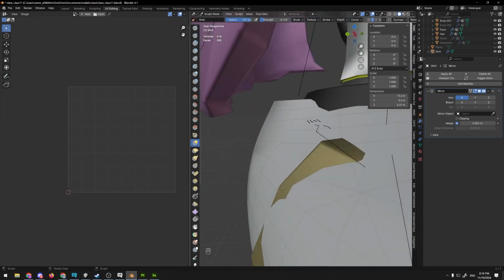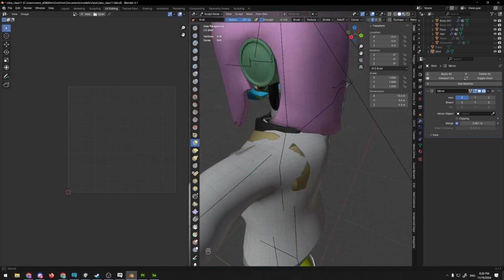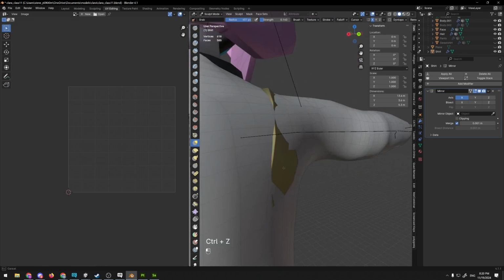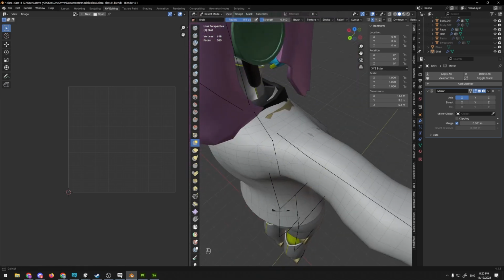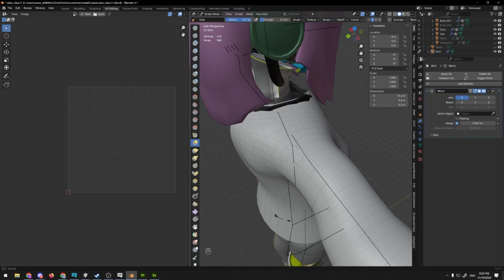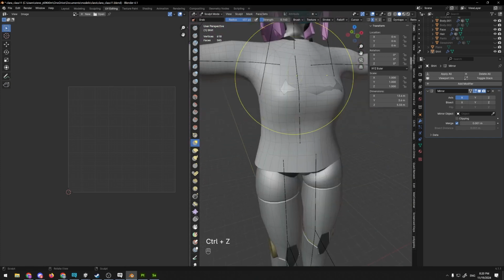This whole section up here, I'm just going to grab and move because, again, smoothing across symmetry lines doesn't work very well until you've applied the mirror modifier. And then, like I mentioned earlier, fixing these areas where we have clipping. Although we are also going to address in this class how to improve clipping in other ways once we get our mesh finished. Any questions while I finish this up?